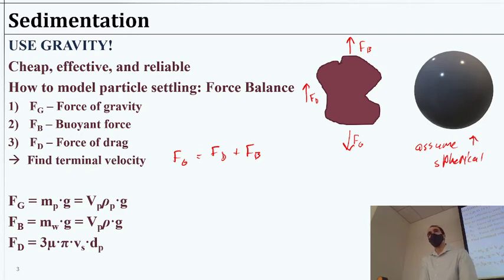If you've ever worked in a lab, maybe you've got a nice laboratory scale and it can go down maybe to milligrams, maybe 0.1 milligrams. If you go really, really fancy, maybe you can get like 0.01 milligrams as your detection limit, and you have to have a very stable surface so there's no vibrations changing your mass detection. Well, consider weighing a speck of dust that's in the water that you're presuming may settle. You're just not going to be able to measure the mass on that. Not to mention you have to take it out of the water.